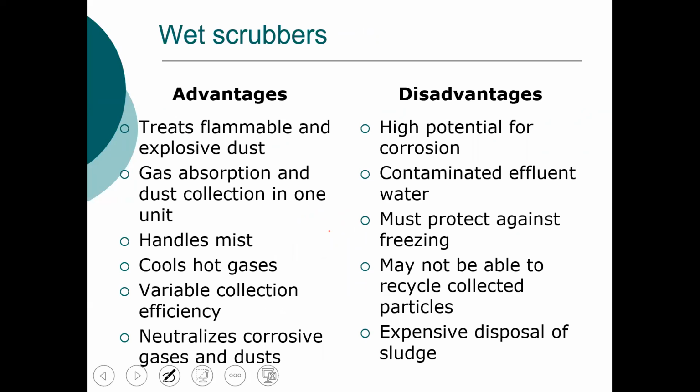One of the major advantages of a wet scrubber is that if you're treating a flammable or an explosive dust, this minimizes the risk of explosions or fires. So it's a significant advantage of this process versus a dry removal process.